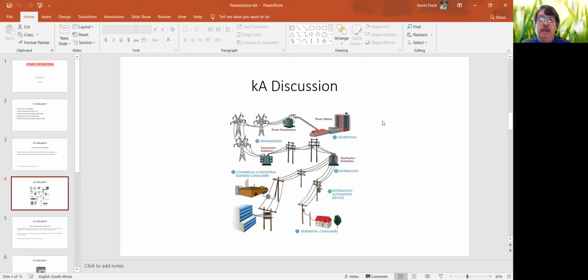Now, a short circuit condition will occur if two phases touch, or a phase goes to ground, ground in South Africa and many countries being a star-point ground, with earth and neutral all in one, so that if any phase touches ground or any phase touches another, there is a dramatic short circuit available.